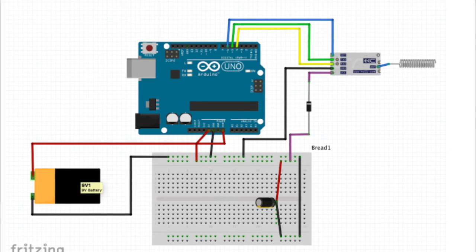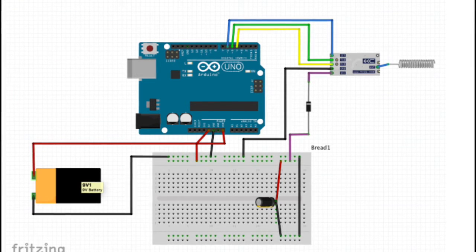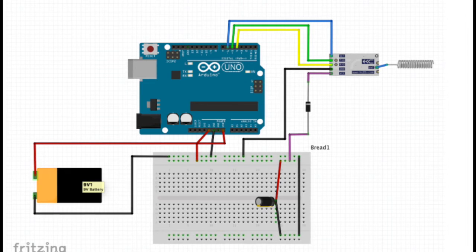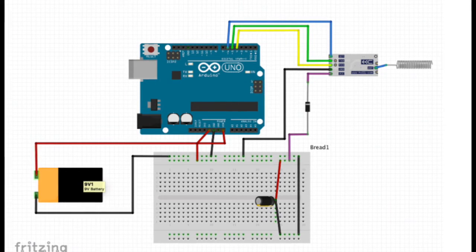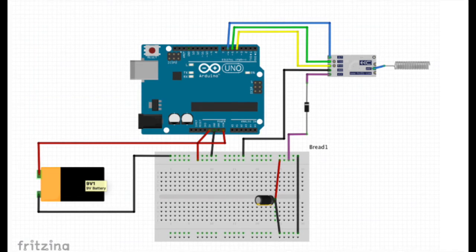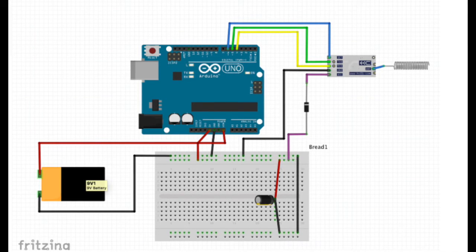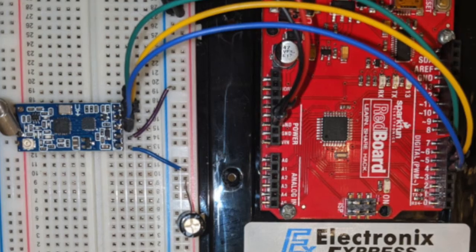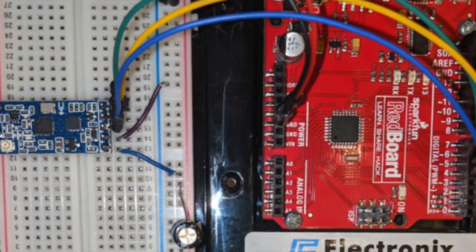Now we will go over some concluding thoughts on the project. We were able to connect all the nodes and collect all 4 flags. There were a couple of challenges we ran into. When changing baud rate, our HC12 would often stop responding to the command line unless it was reset to default. Thus, we were only able to connect the nodes when they were transmitting at the 9600 baud rate.